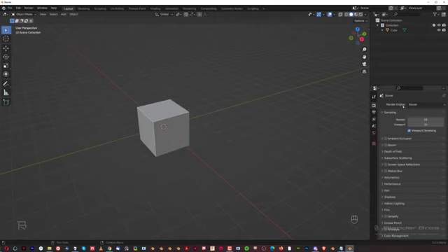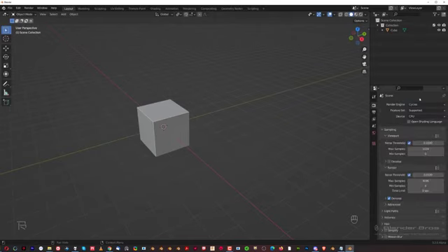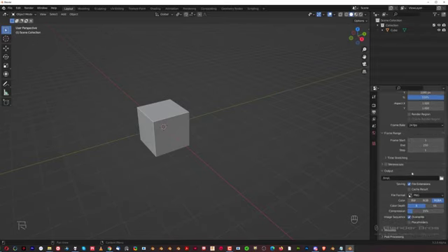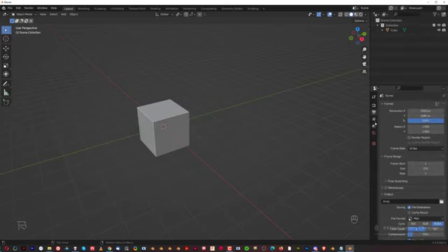So then we can adjust either Eevee or Cycles. There are 2 rendering engines in here. Now, if you're in Cycles, we're of course going to be using GPU compute, but we're going to talk about it later on. Right, so you can switch here between Eevee and Cycles. Cycles is more of a realistic render, and Eevee is more of like a game engine render, like a, you know, real-time sort of a rendering engine. Okay, really great for previews. These are also output settings for renders, so you can set here the size of your image, amount of frames if you're creating animation, because you can create animations, and, you know, image settings, etc. We're gonna be talking about it later on.